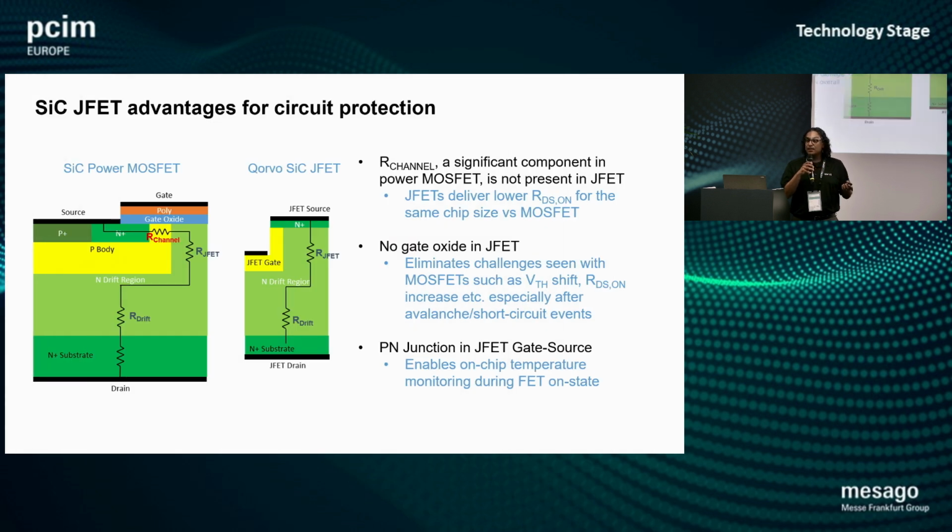Okay. So silicon carbide technology is in the center of all of this because silicon carbide enables you to achieve much, much lower on resistances in a high voltage switch in these industry standard packages than what silicon would allow. You would have to parallel lots of silicon devices to achieve a certain low on resistance, but you could do that with fewer devices with a silicon carbide device. And you're all very familiar with silicon carbide power MOSFET technology. Several suppliers in our show here today offer silicon carbide power MOSFET technology.